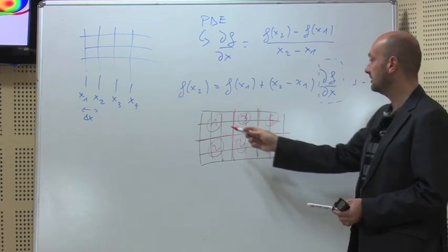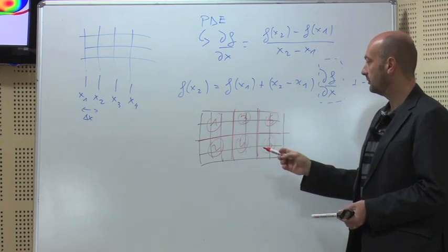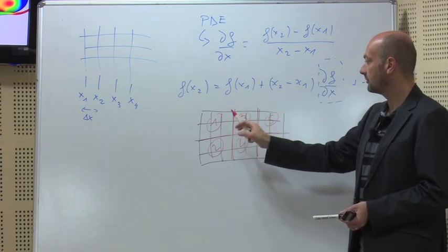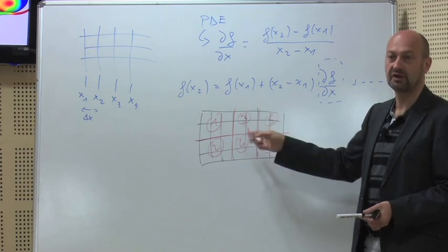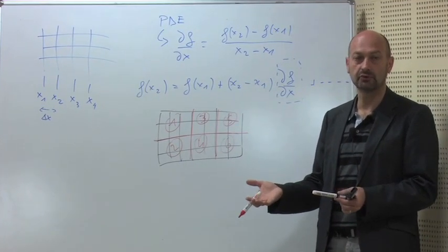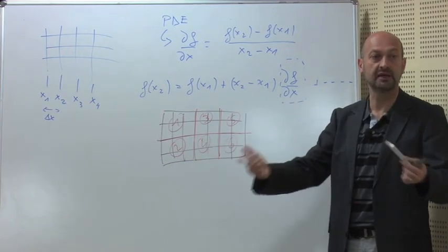You have a domain with many grid cells, and you assign to different processors the job of calculation related to each subdomain. You expect that if you divide the domain by 6, then you divide the computation time by 6, because 6 processors work at the same time.